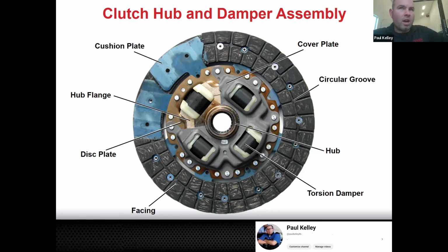If you wear this down to where it's totally worn out, you'll contact the rivets. When the rivets contact the flywheel, that flywheel gets shredded. That's basically going metal to metal. So it doesn't necessarily pay to run this thing till it won't move anymore. It's kind of like when the clutch is slipping, and this is going to go through some of the steps to check. It's really time to go in and fix it. Do the clutch, probably still going to be a clutch kit, but maybe you can save the flywheel.